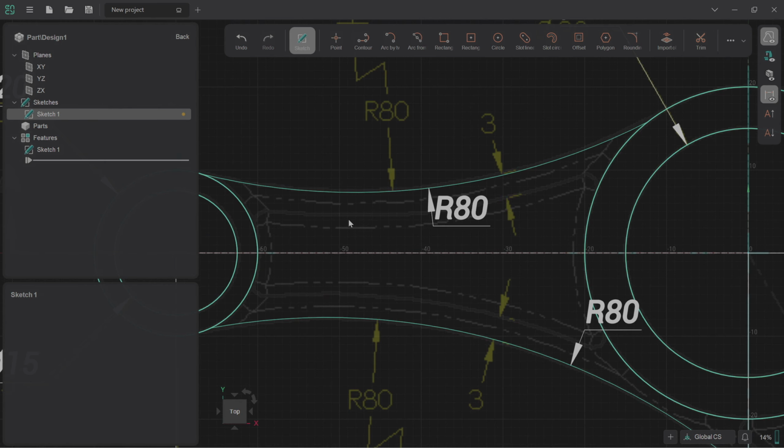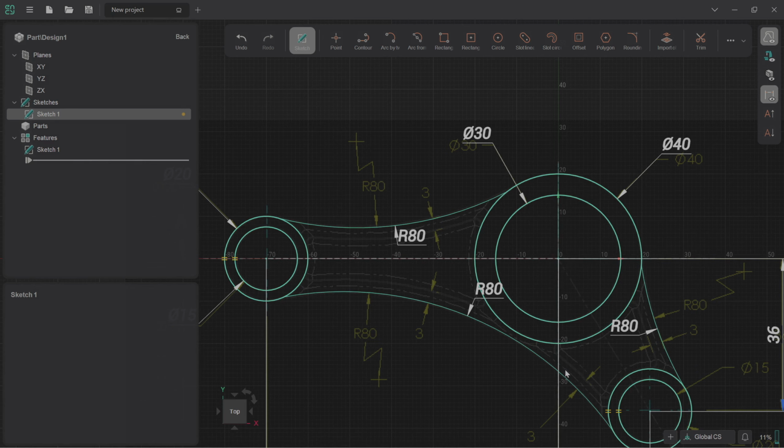So as we've probably noticed, there is also this inner arc line that we want to work to. So there's a couple of ways of achieving this, but I'm just going to go with a simple offset. And to do so, we can either grab all of these, use the offset tool, set the direction, play around with that, or there is a nice little shortcut, which is what I'm going to do here and now. So I'm going to grab the line, I'm going to hold down Control, and I'm going to drag it until this dimension tells me it's 3mm away. Okay, and we're going to do that for each of these, because as I say, it's nice and easy, doesn't require a whole bunch of mouse clicks, and it's just there.